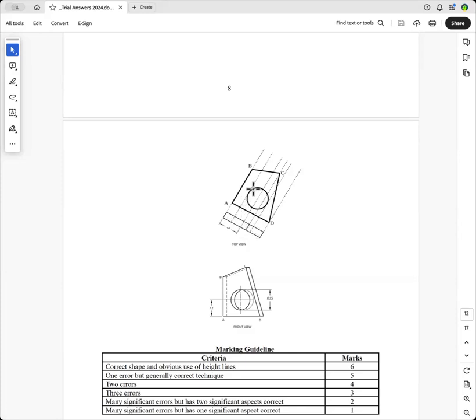Now, if you can get the height as a true length, and you ask yourself, is AB a true length? And you look here and you see that it's a point there. So therefore, all these lines here, these vertical lines, are true length. And so all you had to do is put your compass on this distance here, and you'll get the size of AB. You go from C down to there, that'll be your height there. And so you know that that is the height there, and that's a true length. And that's how you do it.